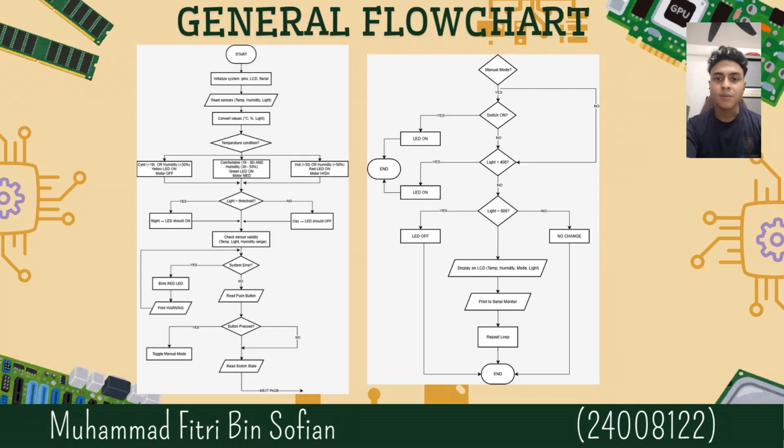First, the system starts by initializing all components like sensor, LCD, and Arduino. It then reads temperature, humidity, and light data and converts them into usable values. Next, the system checks the temperature condition to control LEDs and the motor based on whether it is cool, comfortable, or hot. After that, it checks the light intensity to determine whether the environment is dark or bright. The system also validates sensor readings. If there is an error, a red LED will blink as a warning.